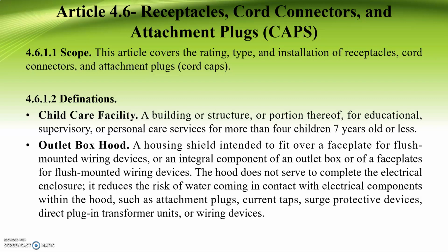The hood does not serve to complete the electrical enclosure. It reduces the risk of water coming in contact with electrical components within the hood, such as attachment plugs, current taps, surge protective devices, direct plug-in transformer units, or wiring devices.